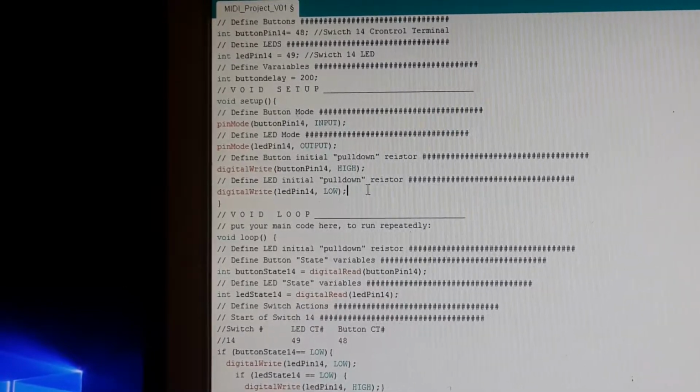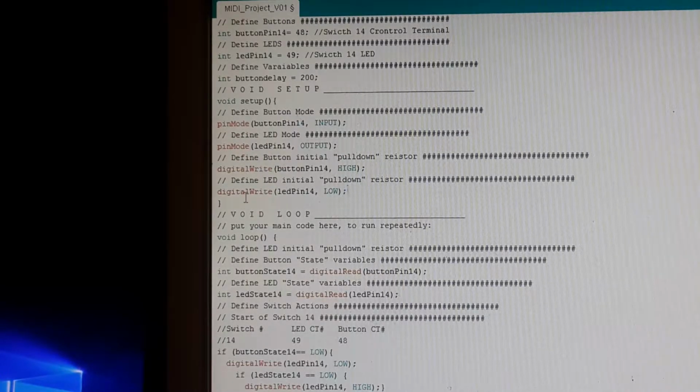Alright, we've got to the bottom of this file, that's why it's not going any further. Void loop, as it says, put your main code in here. It starts off with this statement, as void setup starts off with that statement, and it ends with this curly bracket. You'll get yourself into trouble if you don't know how many curly brackets you have to close off various declarations.